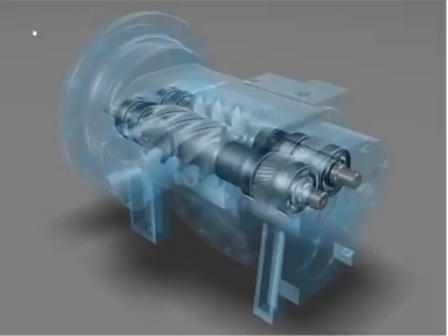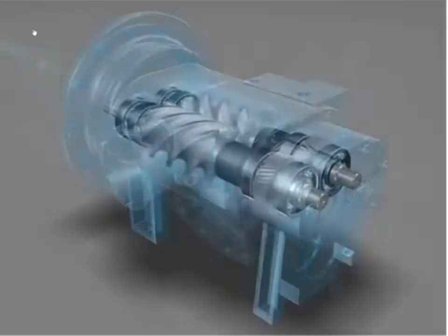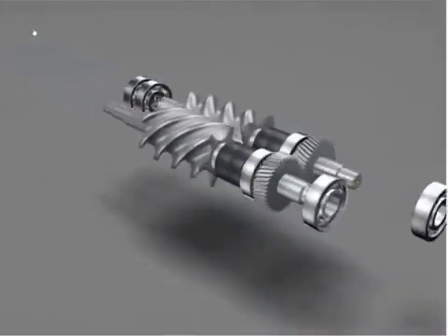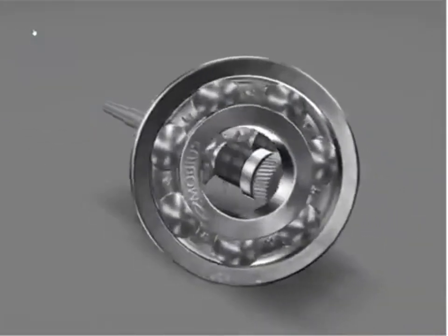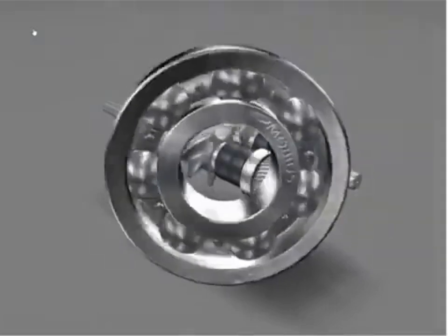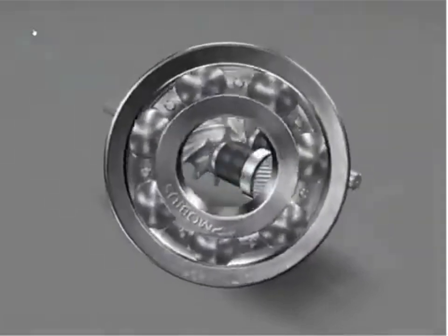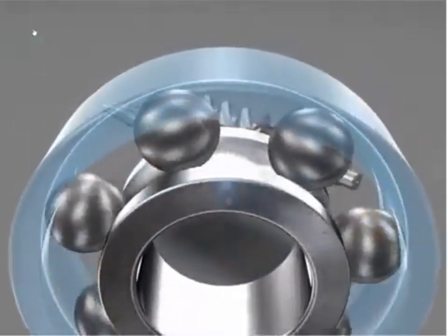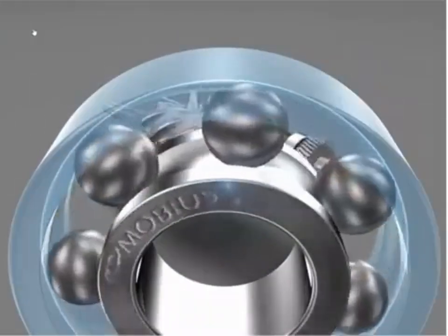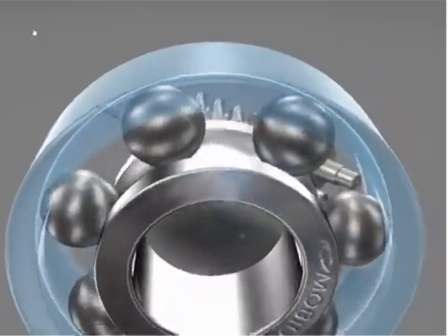So the good news is that when we're dealing with rotating machinery like this, as the rolling elements roll around inside the bearing, they make a certain vibration. The forces involved create a certain vibration pattern when there's a problem. When there's not a problem, actually they don't really create any vibration for the most part.